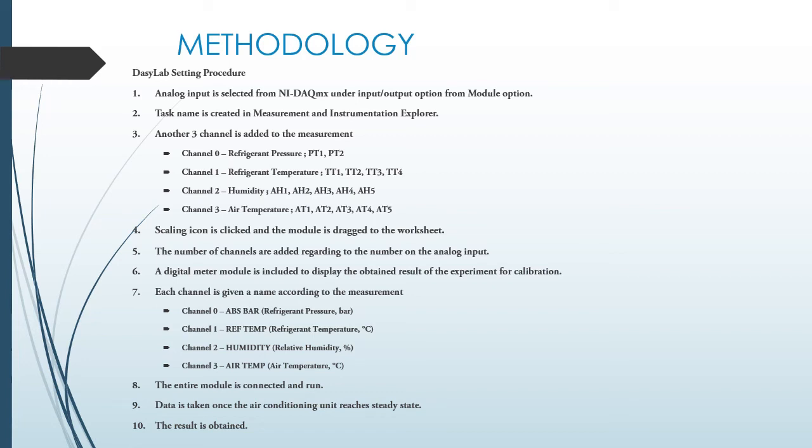Next, the scaling icon is clicked and the module is dragged to the worksheet. The number of channels added corresponds to the number of analog inputs.